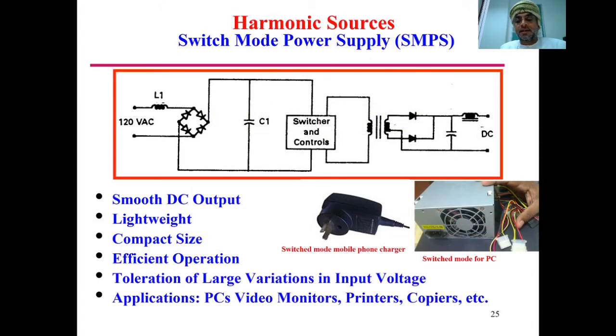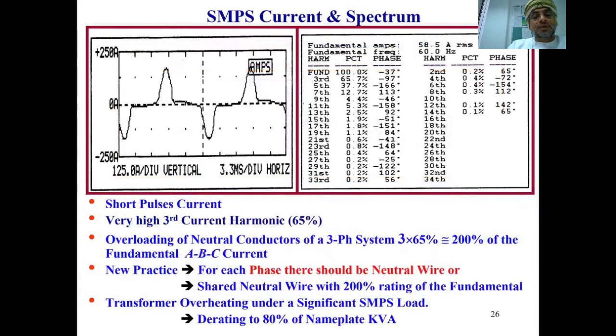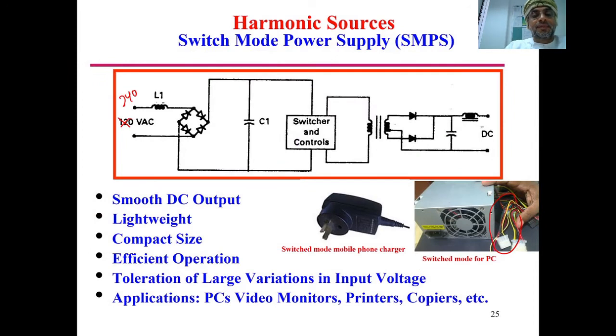And this is the simple circuit for the switch mode power supply. Suppose that you would like to provide energy to your computer. Inside this device, which we call the switch mode power supply, we have this circuit. Since you are plugging the wire to the AC, and in Oman our AC is 240 volt single phase, we have a rectifier over here, a double rectifier.